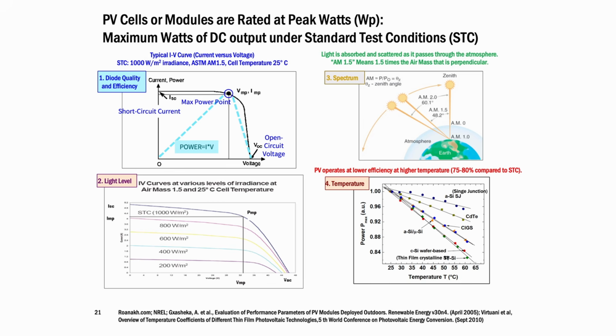In reality, though, out in the field, solar projects don't experience standard test conditions normally, right? 25 degrees Celsius is about 77 degrees Fahrenheit. You can imagine in the desert, solar panels are operating at much higher temperatures. And not all solar panels are at the equator at noon. So solar capacity is often given in DC under these standard test conditions.